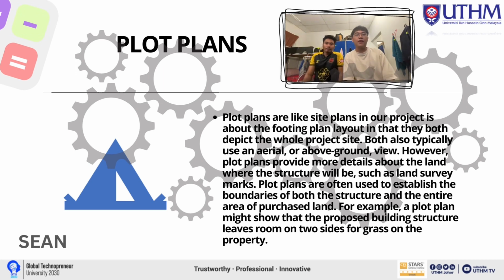Okay, the next is plot plans. The plot plans are like site plans; in our project it is about the footing and layout in the building. Both of these fit the whole project site. Both also typically use an aerial or above-ground view. However, plot plans provide more details about the land where the structure will be, such as land survey marks. Plot plans are often used to establish the boundaries of both the structure and the entire area of purchased land.